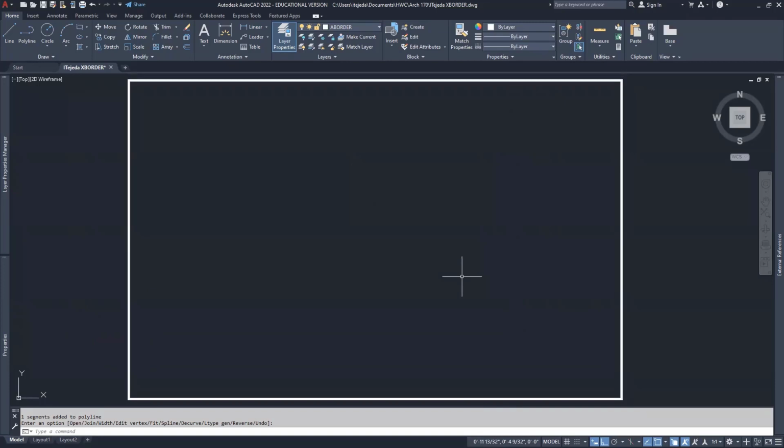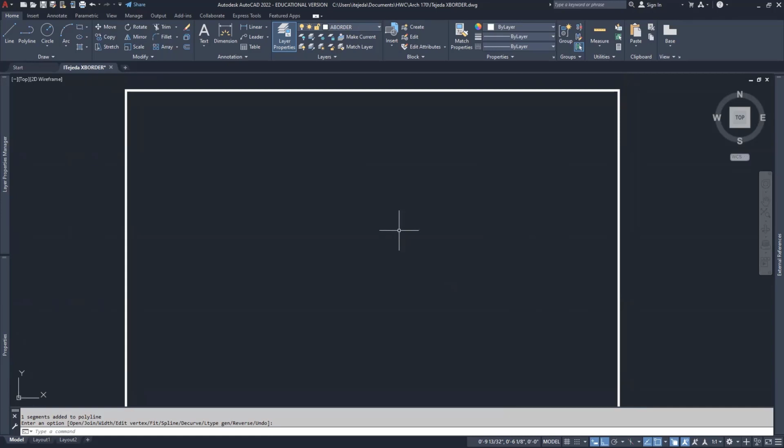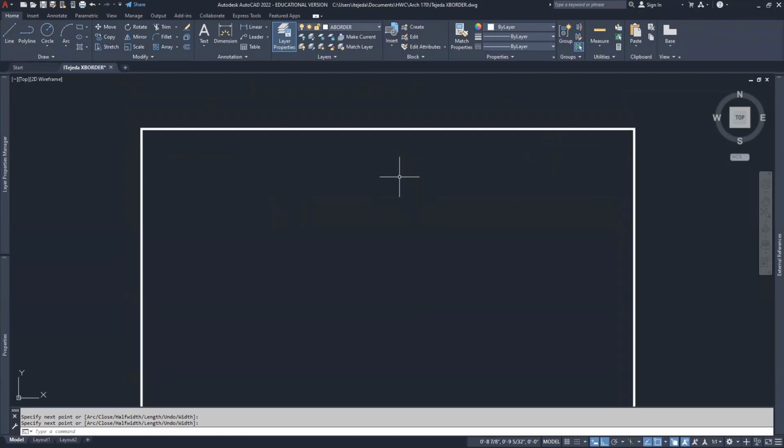If you want, you can do something a little different here as well. And let me show you that for a moment. I'm going to take my polyline. I'm going to click on the icon and I'm going to draw a polyline from this endpoint. Then I'm going to take it to the midpoint and then I'm going to take it to the endpoint. So I've drawn 2 segments to the polyline. I'll enter to terminate the command. And I know I have one polyline on top of another.